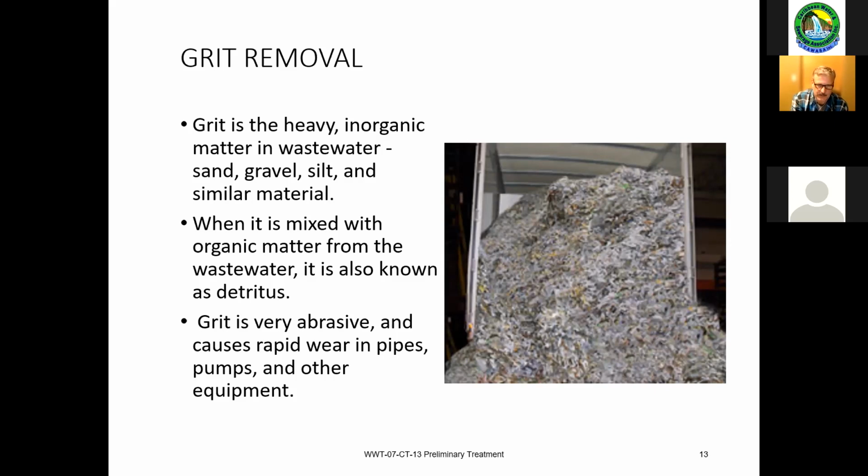When you take grit and clean it or return the organics back to your waste stream, then what's left would just be considered grit. Grit removal is hugely important in the systems for removing that sand and gravel. It will cause immense wear and tear on pumps and mixers through your system. Not only that, after a certain period of time, you'll have grit flowing through, because it's heavier, it'll flow through a tankage. And anywhere that it can settle out, it will, and it'll start building up in corners, and you actually will start reducing the volume of your tank after a while.